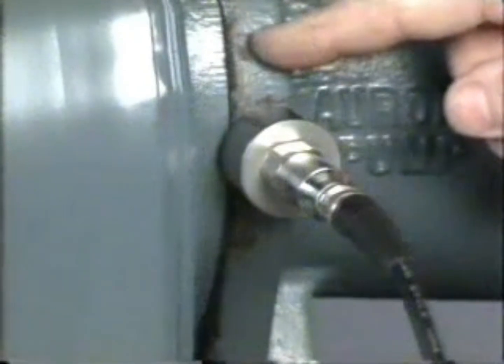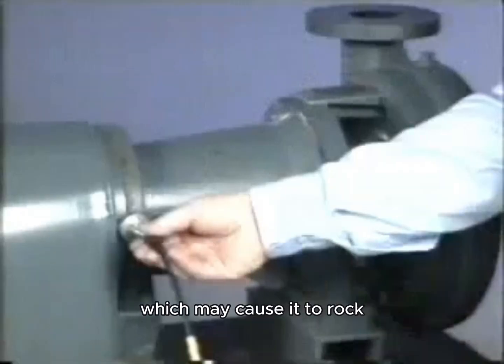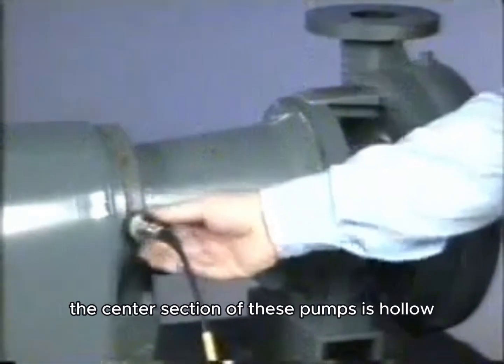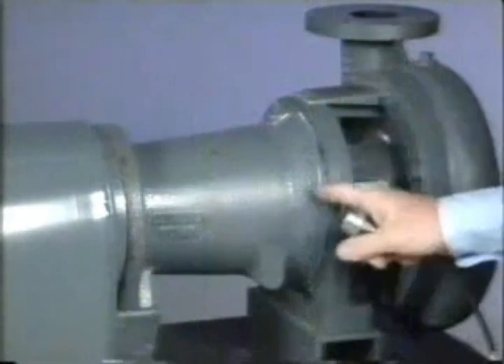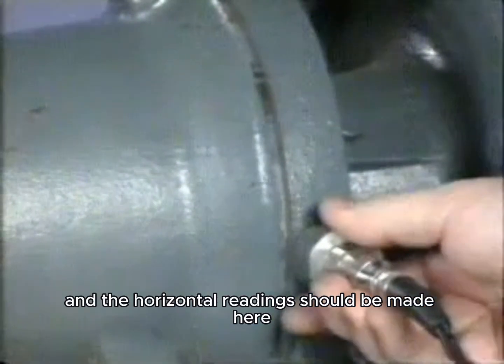Be sure the sensor does not cross the joint, which may cause it to rock and generate erroneous frequencies. The center section of these pumps is hollow, and measurements should not be made here, as the signals will not be accurate. The outboard bearing is located in this area, and the horizontal readings should be made here.